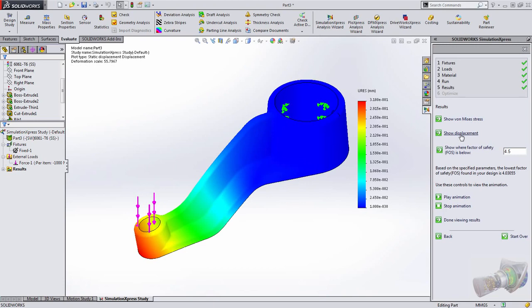But one of the key things that we're looking for is the displacement. And in this case, it's 0.00318 millimeters. We're viewing this in scientific notation, so we'll have to move this 3 decimal places over. So yeah, 0.00318 millimeters is our maximum displacement in this case. So you would then jot down those results.